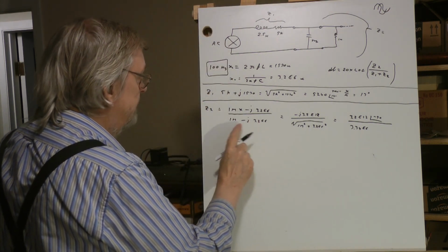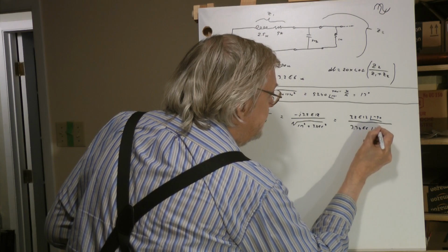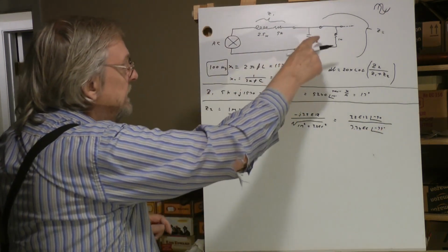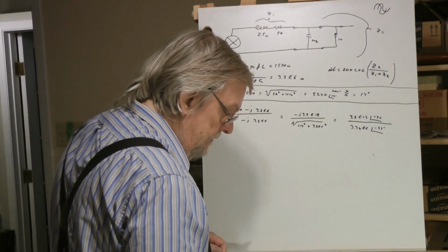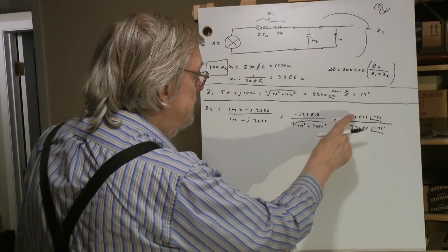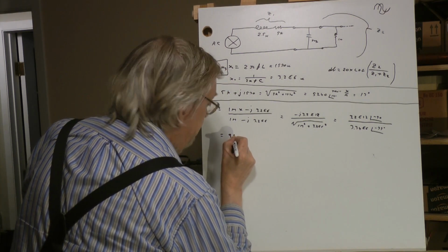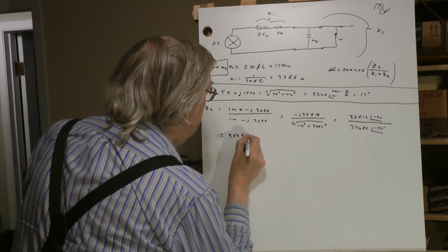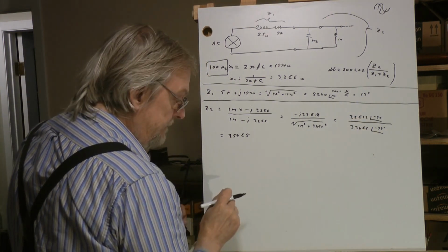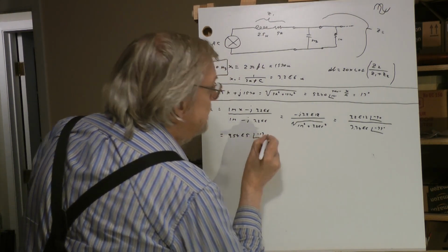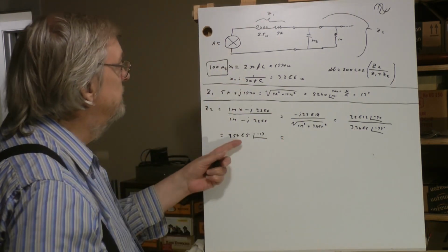arctan of the reactance over the resistance. And where do I got that? Minus 73. Because it's a capacitor, you'll find in these formulas you're almost always going to get negative angles. Okay, so we got to continue along. We have to solve that. That's easy. It's 9.54 E5. So it's 0.9 million, right? And the angle turns out to be minus 17, right? 90 minus 73.